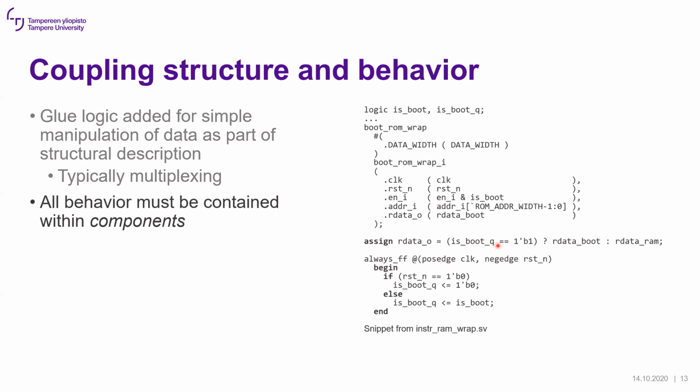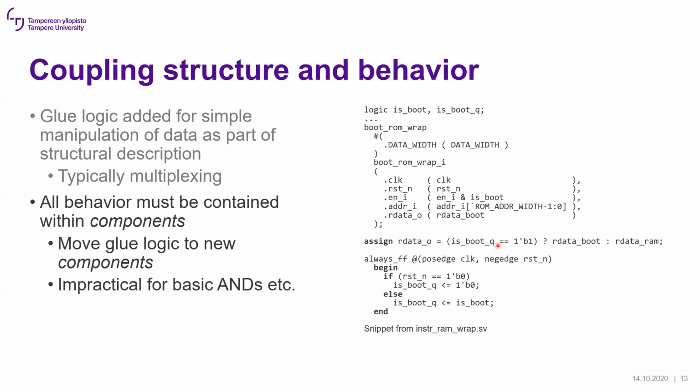However, in IP-XACT, all behavior must be contained within components. There's no behavior in designs. So in practice, we have to move all this glue logic to new components. However, it must be said, this is impractical if we are doing basic ANDs or such.